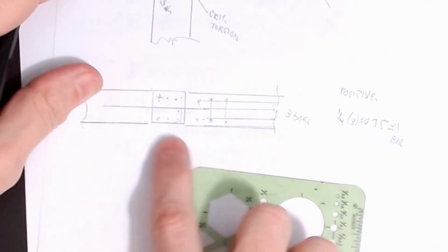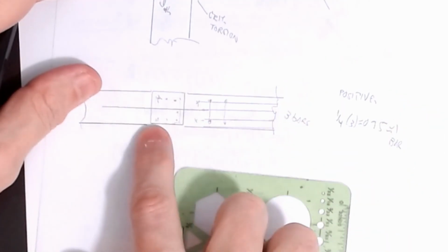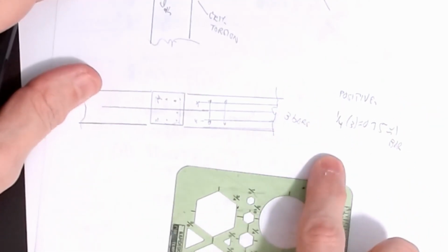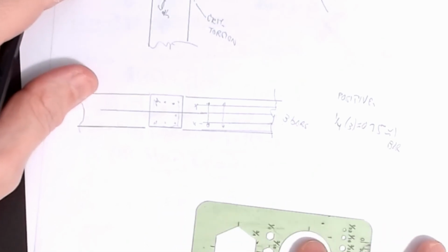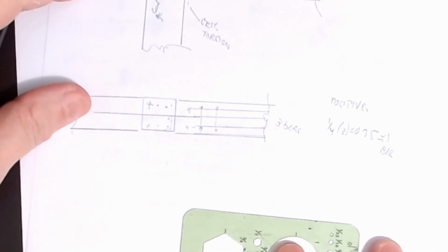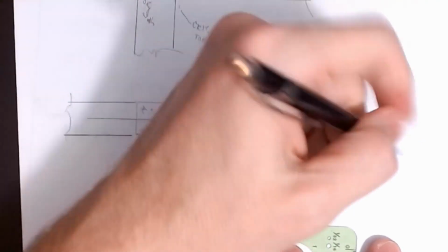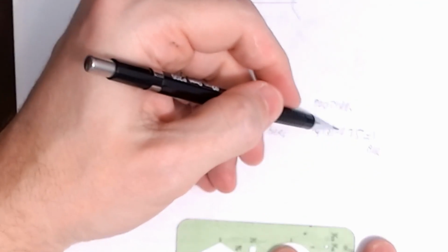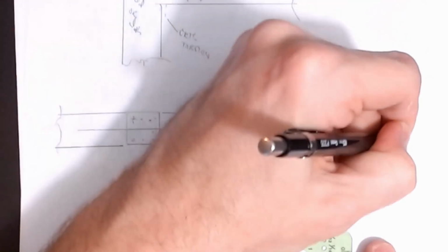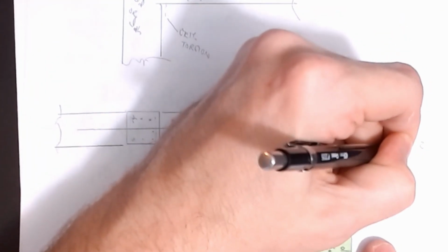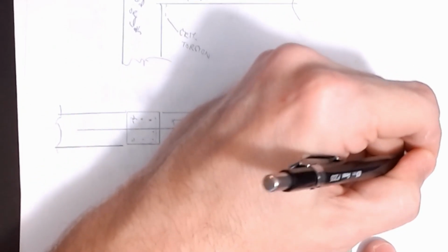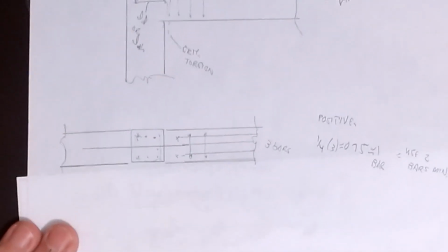So there's a certain amount: 1/4 of the positive moment, 1/6 of the negative, but not less than 2 bars. And it's not less than 2 bars for the positives as well. So when my calculation said 0.75, we must use 2 bars minimum.